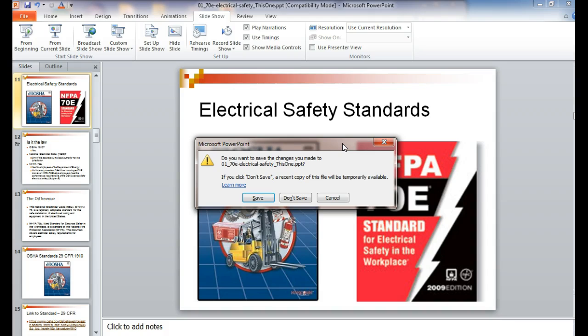But it has one power plug. So we literally could kill power at the outlet. But we've also got a plug-in cord lockout that you can actually put the plug in and lock it. But the Festo line's got individual power supplies for each station. So you have to have the key code? No, the key is used to switch it between manual and auto. Now there's a version of it that supports e-stop, but when I was looking at the documents, they talked about it being optional. I was going to say, if the key turns it off, you've got a lockbox. Yeah, you just hang the lock in the lockbox and put the keys in the lockbox. But no, those keys are not suitable, so we don't have the ability to lock and tag.